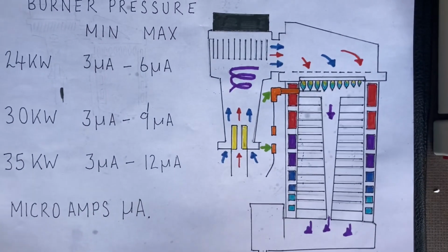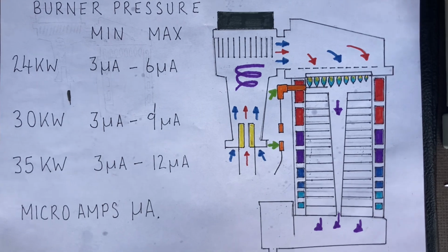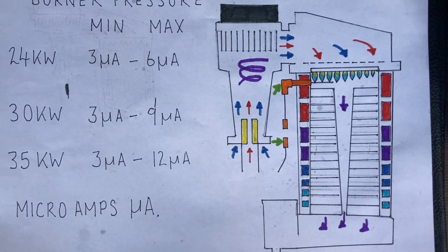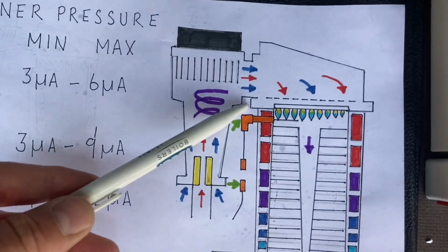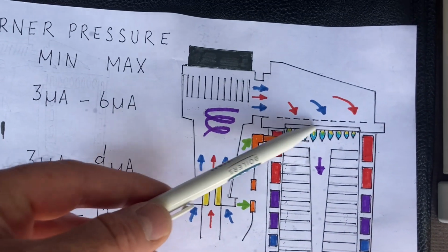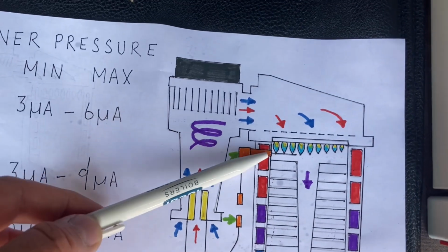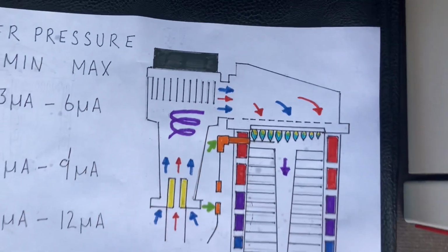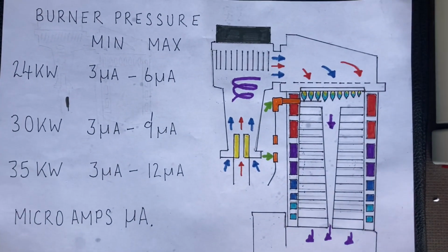What happened, obviously, after speaking to the customer, is that this cat lives there. The bung was removed, and it was just sucking cat air in, and it got stuck in the baffle plates, between the baffle plates here and the ceramic plates there, and it just blocked it up. So rather than on maximum, we weren't getting a flame like this, we were getting a flame like this. So when I swapped the burner, it worked. And from then on out,